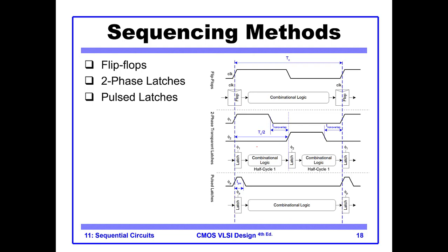Now there are different ways in which you can design your sequential logic. In fact, there are 3 ways in the book. One is that your model is like this, that you have register R1 and register R2, and inside these 2 registers you have your combinational logic. This is one way, and this is predominantly the most used way. So all your logic is inside flip-flops.